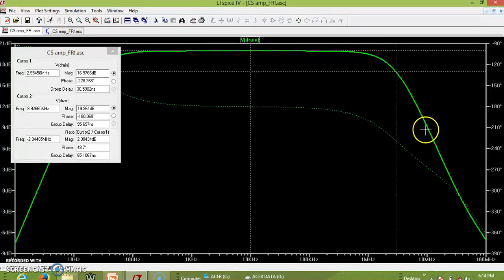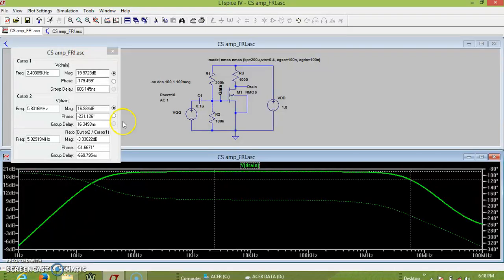When those two frequencies, F1 and F2, are very close, it is a bit difficult to get the exact cutoff frequency at this point. So let us move the value of RS to a lower value and try to see whether this 530 will become 5.3 or not. Just observe that I made the R series resistance just now 10 ohms.